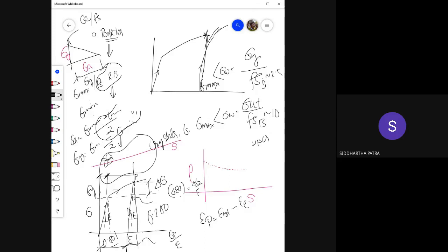But you see, ductile materials can take a little bit of plastic deformation, and they could be going through a fatigue cycle with plastic deformation. Maybe a very tiny amount of strain, but they can have that much plastic strain, and sometimes having that much plastic strain is not avoidable.